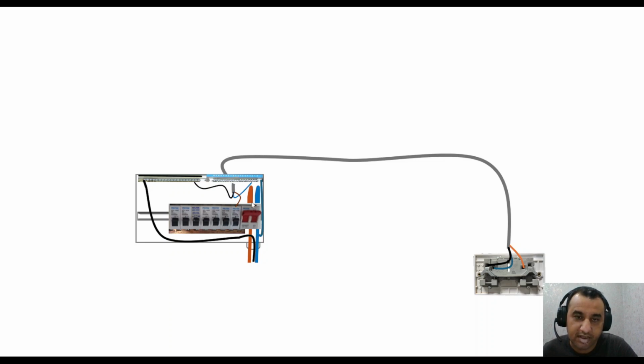The cable from the meter tails feeds to this main switch, and from the bottom end of the main switch there's a cable connected to this neutral terminal. All these circuits' neutrals are going to be connected here, and their line conductors go to the MCBs, whichever they may be: a cooker circuit, shower, lighting, sockets. Their CPC, circuit protective conductor, the earth cable, will be connected to this earthing terminal.